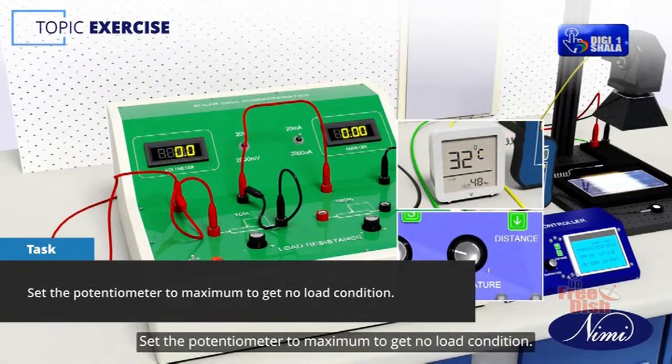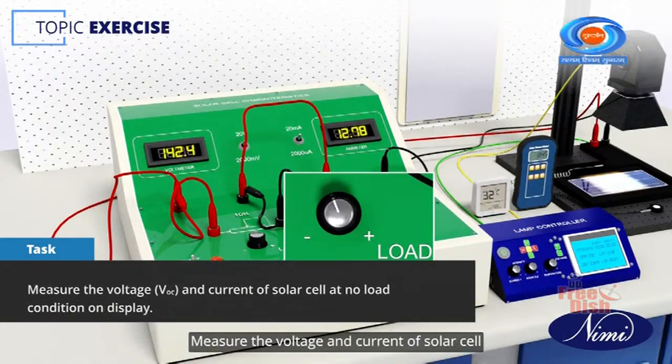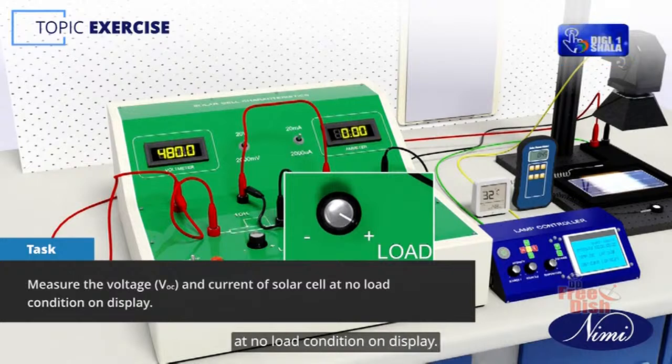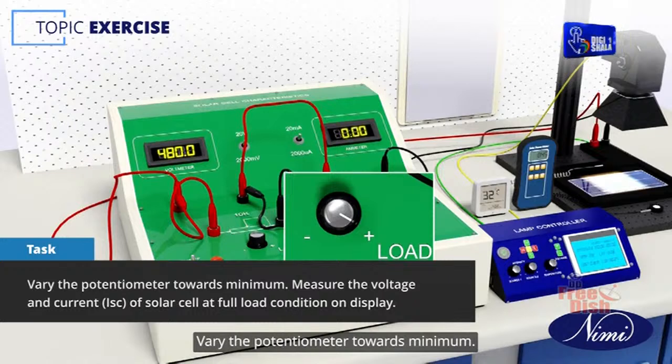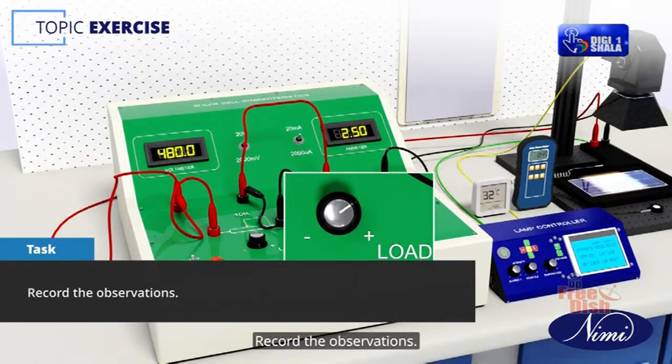Set the potentiometer to maximum to get no load condition. Measure the voltage and current of solar cell at no load condition on display. Vary the potentiometer towards minimum. Measure the voltage and current of solar cell at full load condition on display. Record the observations.